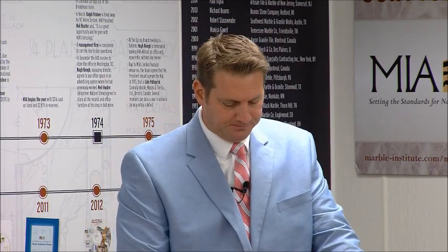So if I'm going to hang travertine on an exterior wall in a cladding, mechanically anchored cladding format, I better make sure that as the architect I'm requiring in the specifications that ASTM C880, for example, is included, so that we are all getting that full information that we need. So that's it. They're going to put this in the plans and specs and send it out to the world to go to the GCs, and they send it out to their subcontractor world. We want to make sure that that spec has all the information in it that is going to be necessary to get a proper and responsive bid.